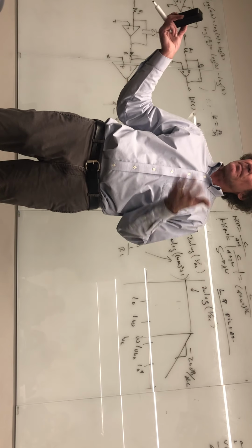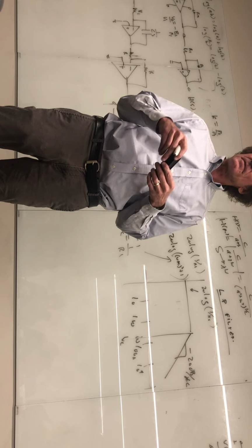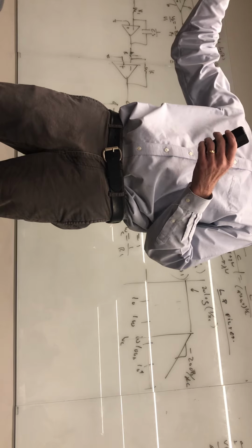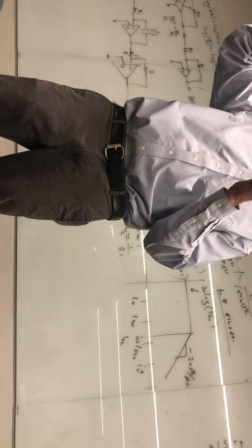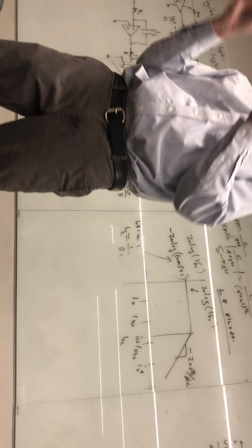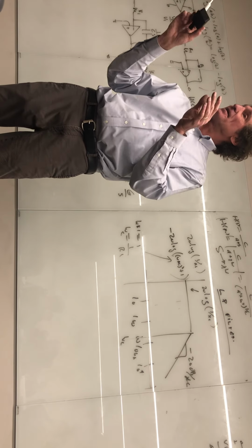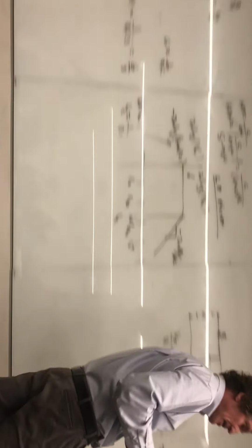You all had filters, right? Low pass, high pass, band pass. Well, with amplifiers, what I want is if I know how my speakers behave, I know what their H of S is, so to speak. I want 1 over H of S multiplying that so that now my sound is flat. Does this make sense, at least in concept? And so now I can design into my sound processing something that's going to do just that. So my speakers are going to give me perfectly flat, clear sound.